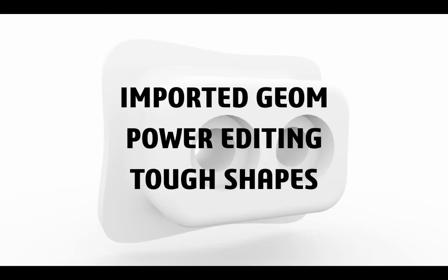We needed to move the snap clip. And I realized, to parametrically edit that snap clip and just move it up just a little bit was going to be really painful. So I just used the multi-body method and chopped it off, split the bodies, moved it, knit it back together, done. Okay, it's not the most elegant, but sometimes you just got to get things done quickly, right?